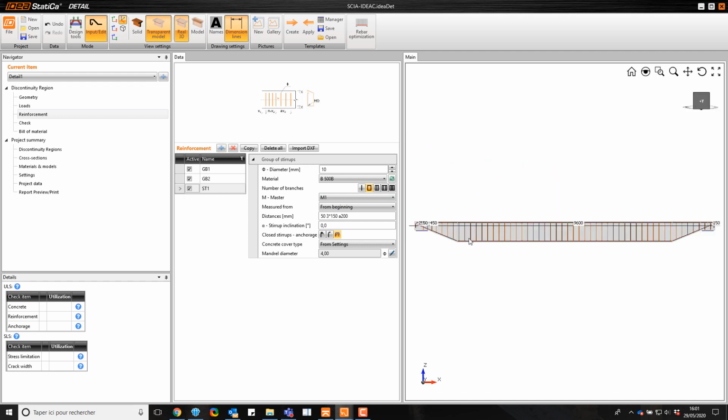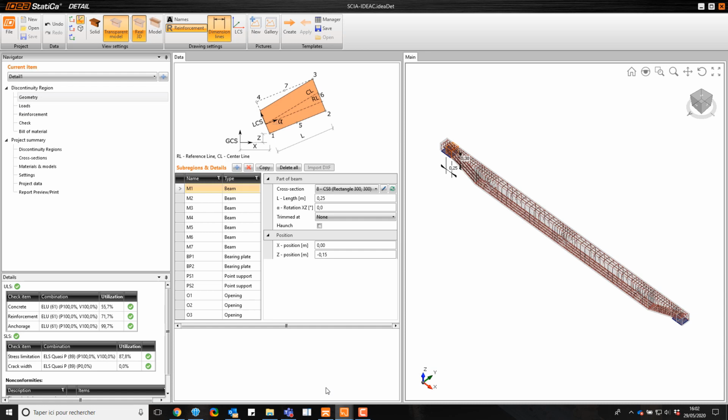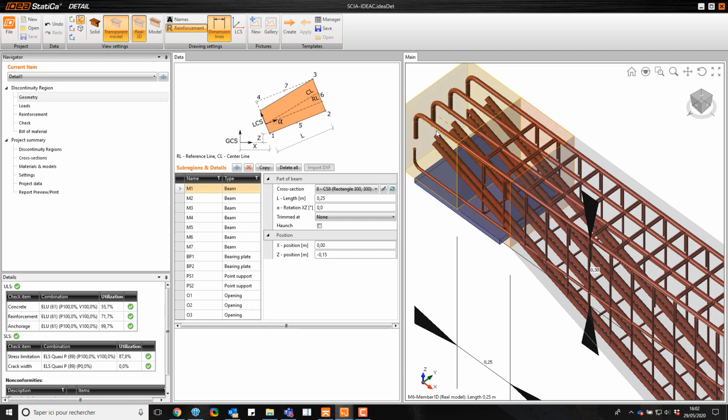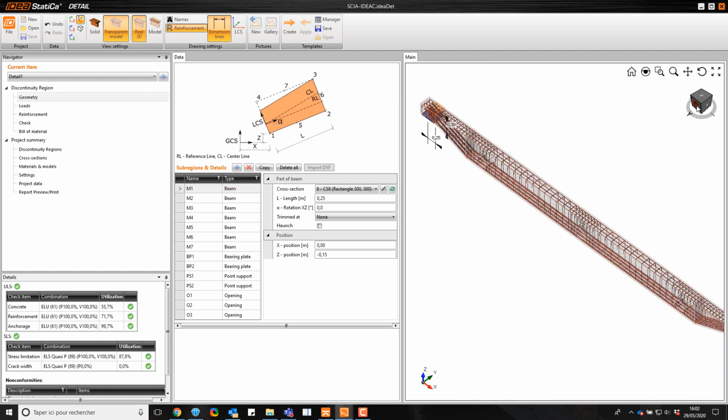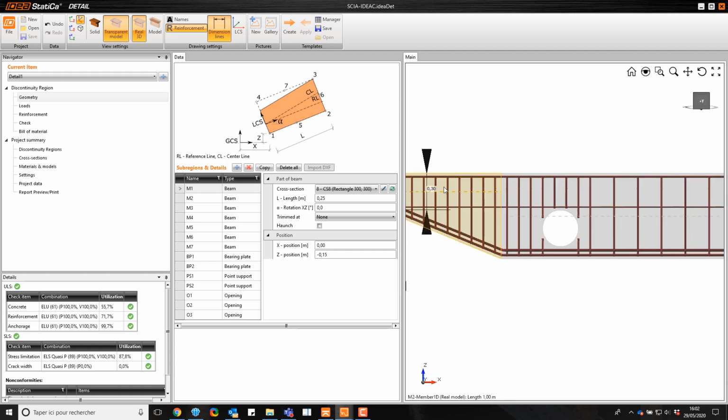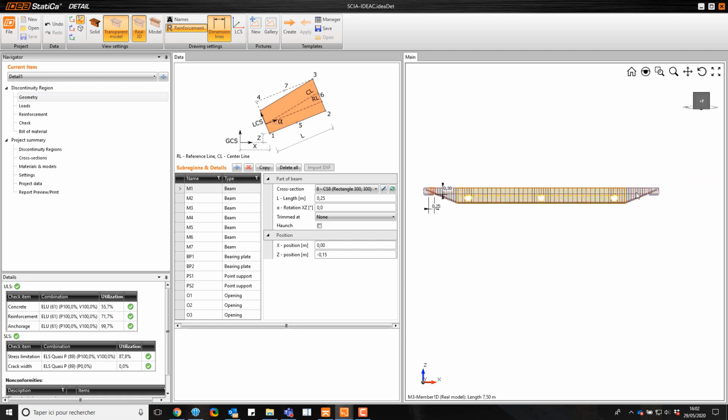This is a little bit the model if I want to treat it like that, and there's already a spacing done. I'll take the other model. This one is the complete one. I add also a couple of holes in the beam. So here you go. The spacing of the stirrups now is already set correctly, and also the different rebars.